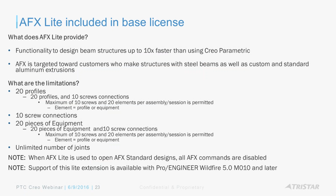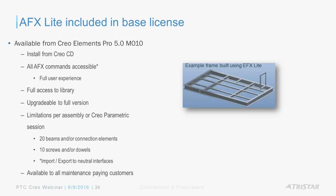Now, earlier I talked about AFX Lite, which is included in the base license. So pretty much all of you that are currently using Creo Parametric should be able to access AFX Lite, right? It does have some limitations, like up to 20 profiles, up to 10 connections, etc. But in the full license, you don't have these limitations, obviously, and this has been there since Pro Engineer Wildfire 5.0 M010, the maintenance date code 10, from which you were able to access AFX Lite.